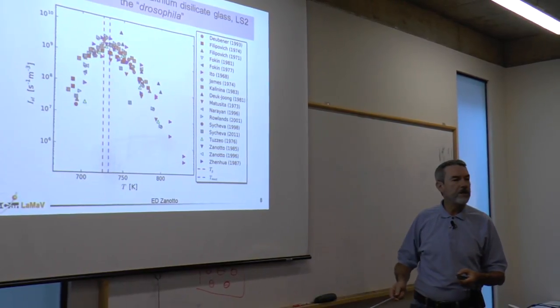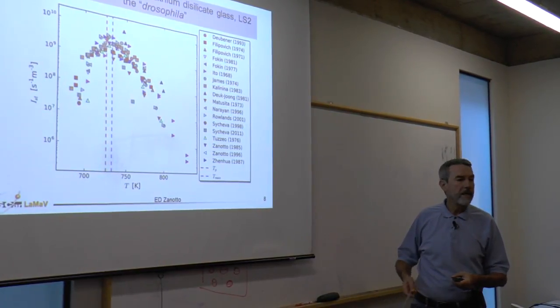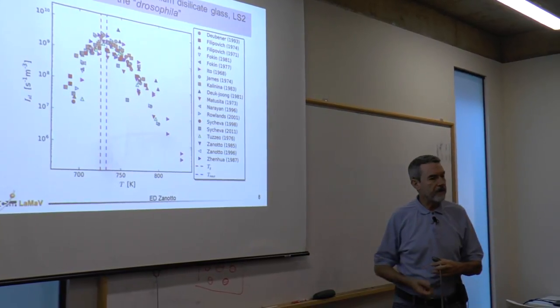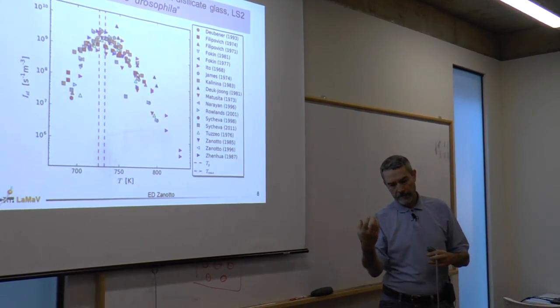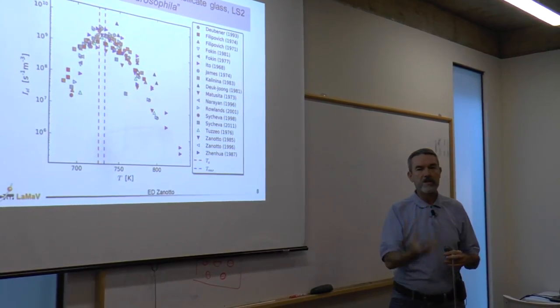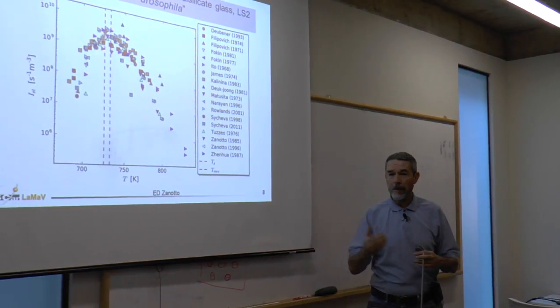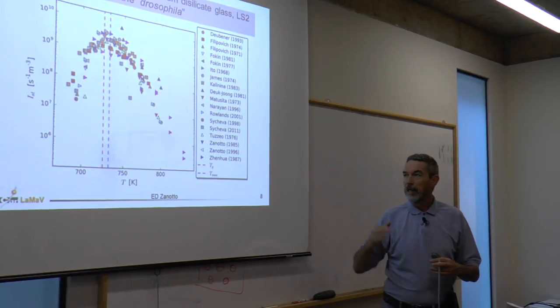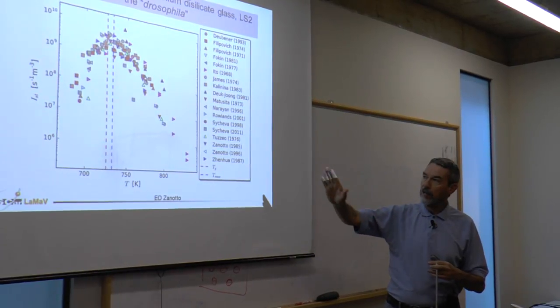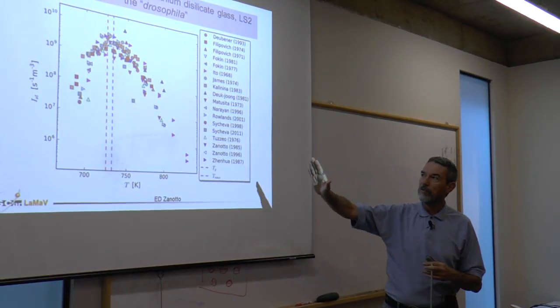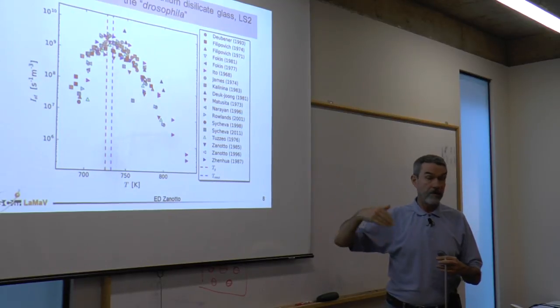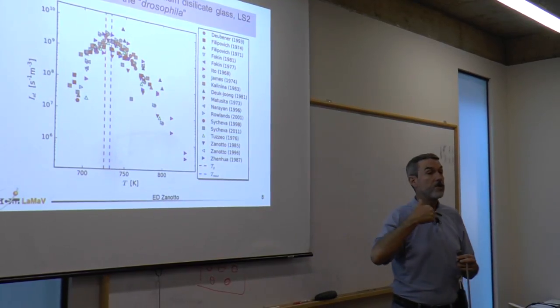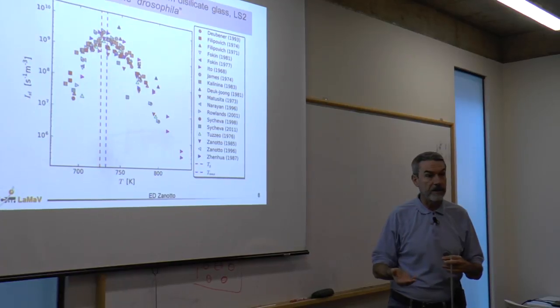If we had heterogeneous nucleation, then as the crystal-liquid surface energy depends a lot on the wetting angle, these nucleation rate curves would be shifted because the nucleation rate depends strongly on the surface energy.